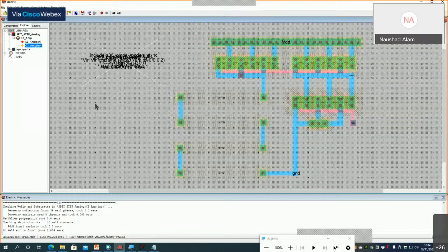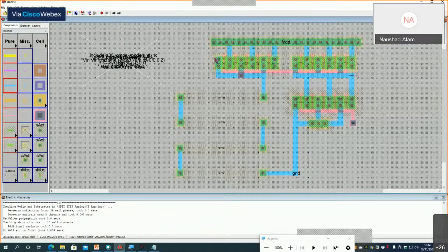There is no problem putting the well after the PMOS and NMOS transistors are placed, because generally you start with silicon material, then have these two wells and then embed the transistors in that. Now we have placed the wells after we placed the transistor, so there is no problem while doing the layout. The P MOSFET that we picked from the component is already placed in the well, and this is the well contact. Without defining the wells first, we place the transistor and then place the wells, so there is no problem.